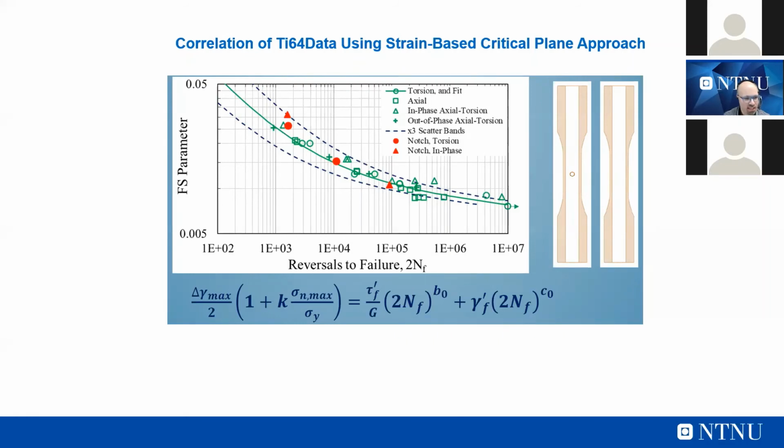strain energy density does not need to take into account which is the critical plane. And for finding a critical plane in a complex geometry, you need 3 days. So from my point of view, the strain energy density has some advantages with respect to the critical plane approach and the Fatemi-Socie approach. But on the other side, we can less motivate the physics behind this approach, and this is for sure another truth. So I want to leave you with this open consideration.